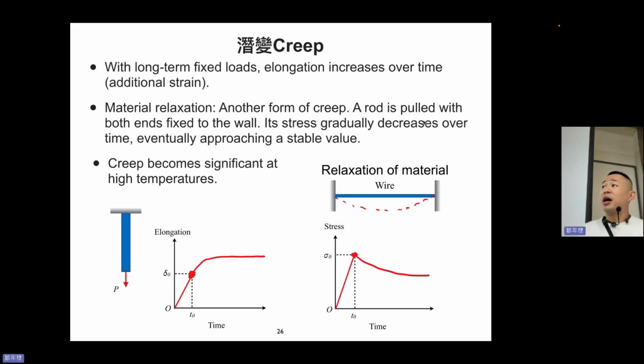Also, creep is a kind of high-temperature effect. If you have higher temperature, creep will affect the material more significantly. You can imagine that because of the higher temperature, the atoms in the material shake harder, so it will release the stress even more. Okay.